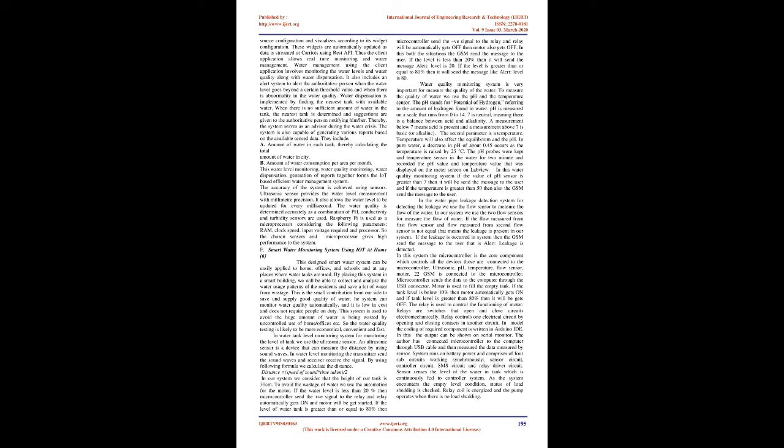In the water tank level monitoring system, for monitoring the level of the tank we use the ultrasonic sensor. An ultrasonic sensor is a device that can measure the distance by using sound waves. In water level monitoring, the transmitter sends the sound waves and the receiver receives the signal. By using the following formula we calculate the distance. Distance equals speed of sound times time taken, divided by 2.